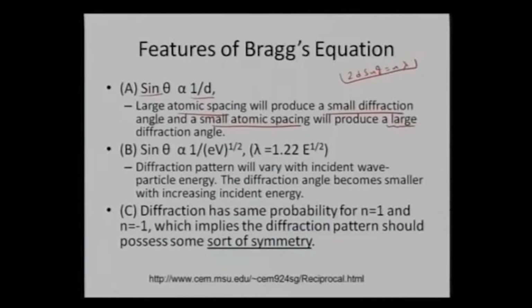Secondly, for a particular interplanar spacing, I can also see that my sin theta is proportional to my lambda, or inversely related to my energy. If I start increasing my lambda, or decreasing my energy, then my theta will increase. And as my energy is higher, my lambda is lower, so eventually my theta also has to decrease.